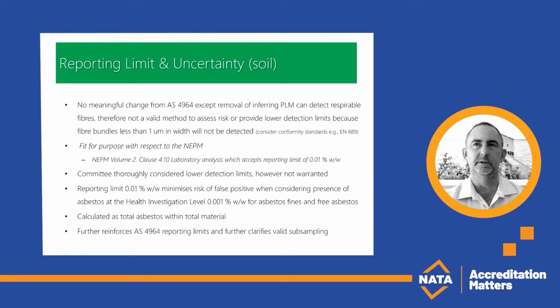And then when we look at soil, there's essentially no change in the process to soil analysis, except to emphasise that polarised light microscopy overlooks a significant population of respirable fibres. And in our review, we carefully considered the National Environment Protection Measures, specifically referencing Volume 2, Clause 4.10, which accepts a reporting limit of 0.01%.